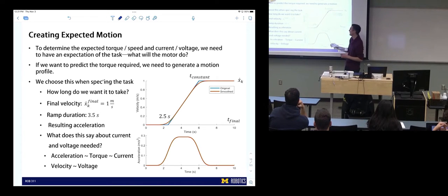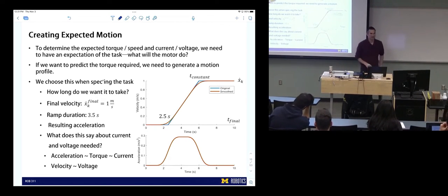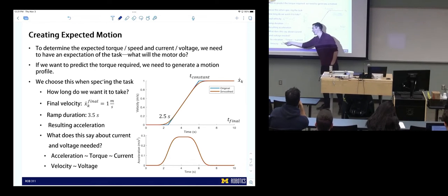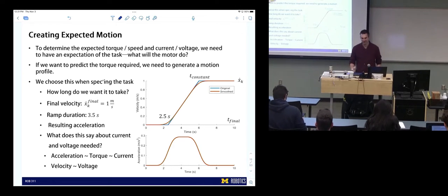Yeah, so this is easy to code in MATLAB, but not realistic physically, because it has sharp corners which require infinite acceleration. So I smoothed it with the MATLAB function and it gave us this. The way it did smoothing was a moving average window, which gave us blips in the next plot. This is also really important: acceleration is proportional to torque, proportional to current in general, and velocity is proportional to voltage in general.